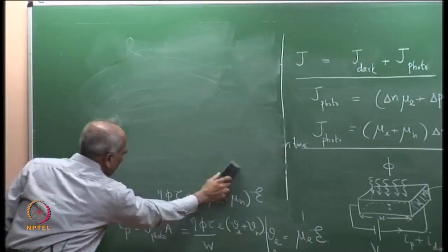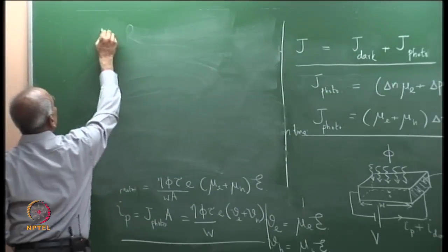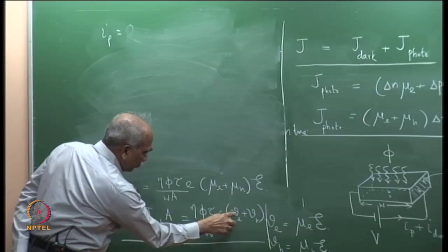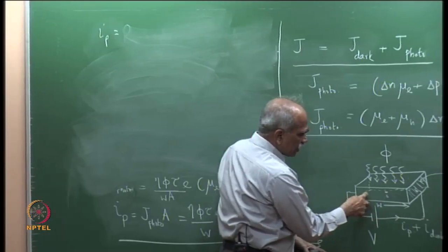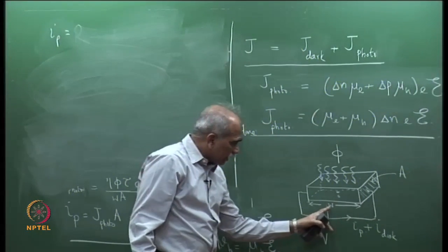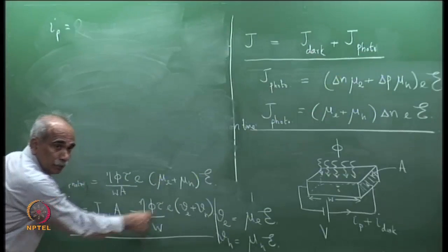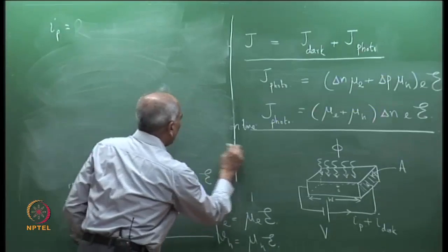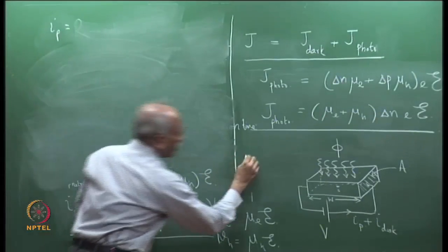Otherwise, you can simplify this very rapidly. So, I_P is equal to, now please see that V_E by W, where W is the width and V_E is the velocity with which the electrons travel, and therefore that represents time. So, W by V_E is the transit time of electrons.